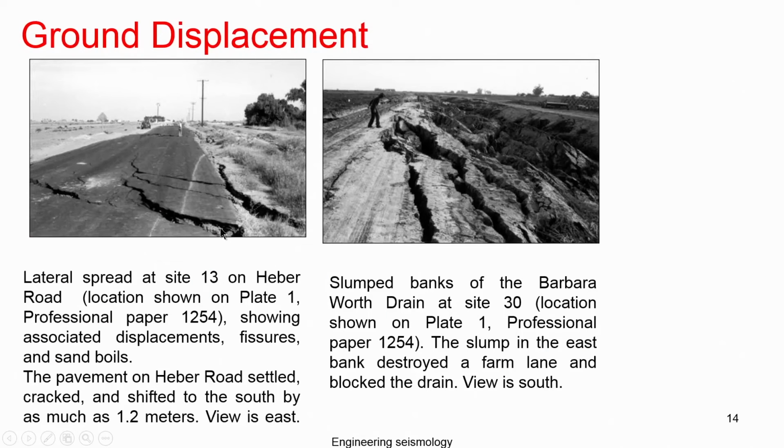So, then next is the ground displacement. The ground displacement is a permanent displacement caused in the ground due to the earthquake, which happens generally because, as we know, the soil is actually an assemblage of particles. Okay. So, this particle size varies from 2 micron, 3 micron at the lowest size to 50 mm, 100 mm, 200 mm at the largest size. It depends upon the geological formation and which area it is, all those things.